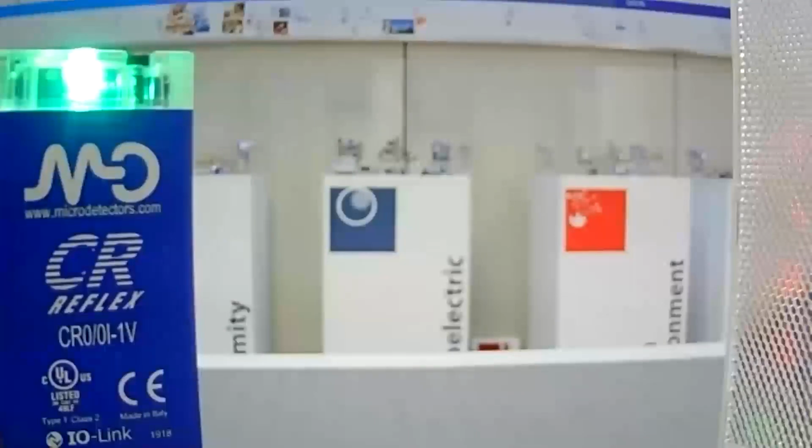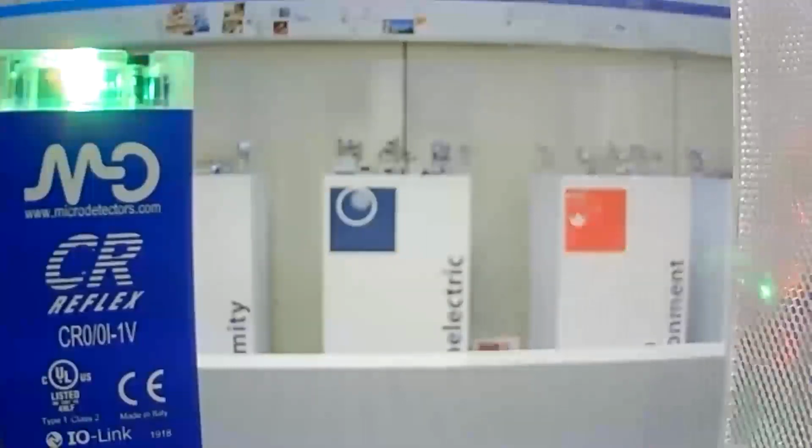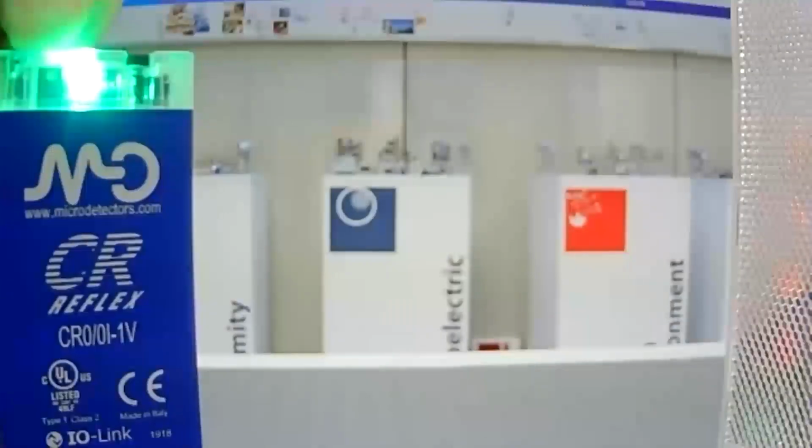The standard teach is the one that you can normally use for 80% or 90% of your applications. Only in very particular cases, like detecting a transparent object like this one, is it better to use a different type of teaching. That is the long teaching, or fine teaching.